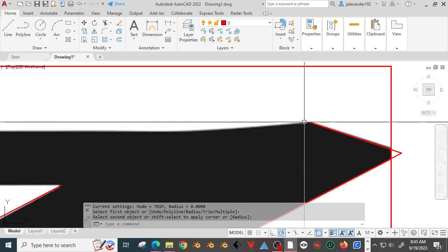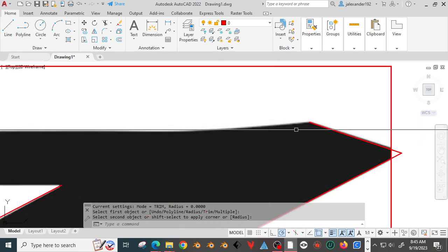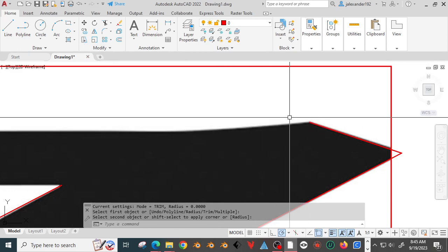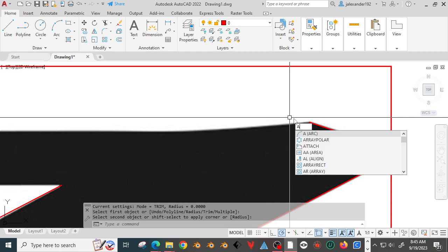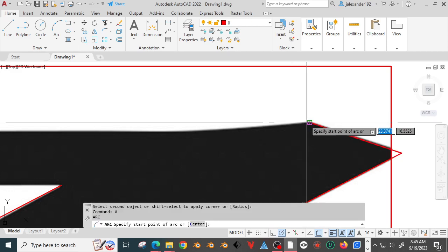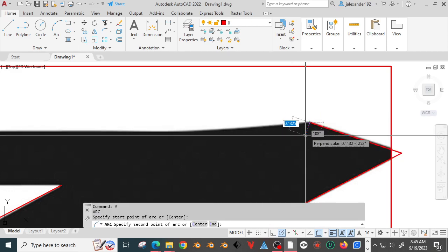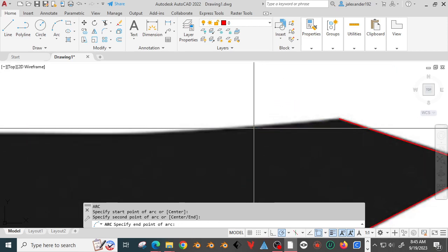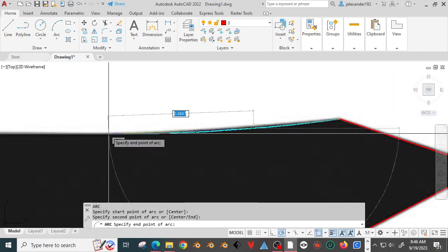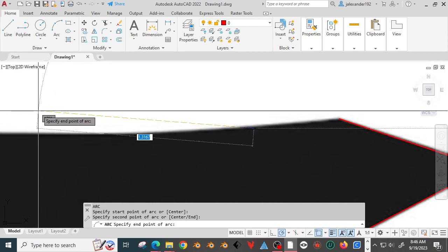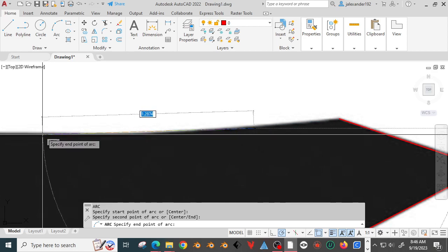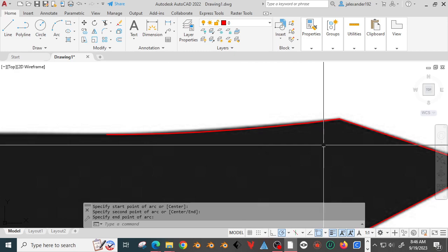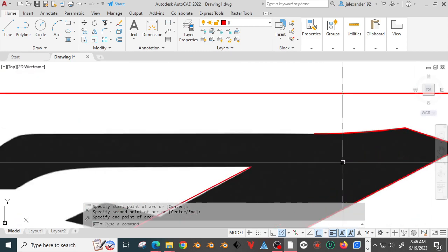All right, now here, that's actually a curve. So let's draw our first arc. I'm going to just type A for arc, and then space. So I'm clicking 1. I'm going to click, basically just tracing this, clicking 2, and then trying to estimate where the arc ends. And you can see, at a certain point, it stops fitting. So I'm going to guess here. We can always edit it after the fact. It's a little arc there.